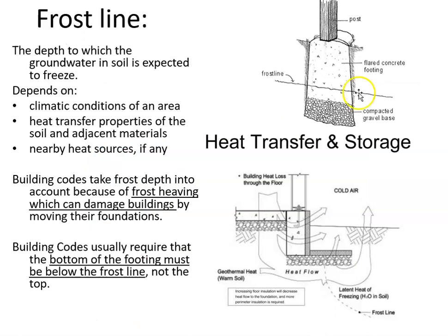All right, so in general, foundations need to reach below the frost line. Very important, okay? That is the depth to which groundwater in soil is expected to freeze. Depending on the climatic conditions in the area and the heat transfer properties in the very, very local area, the township that you live in and what part of the state you live in all affect the frost line, but also the immediate area right around the house could affect exactly where things are freezing or not freezing.